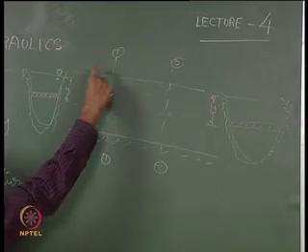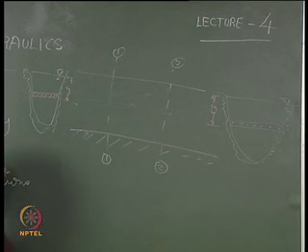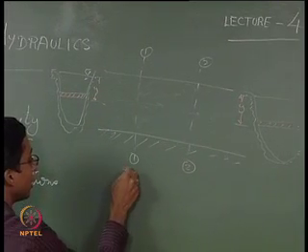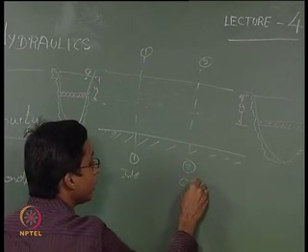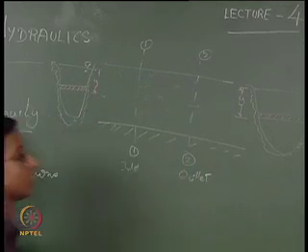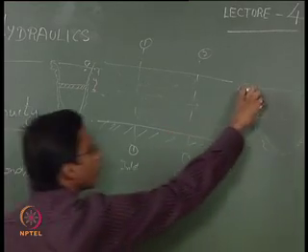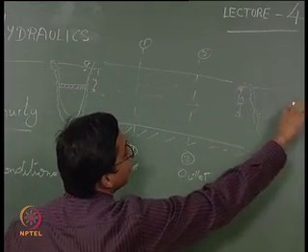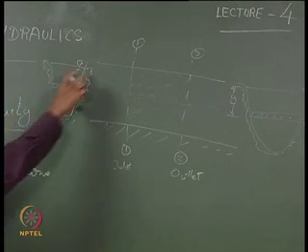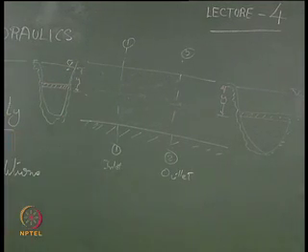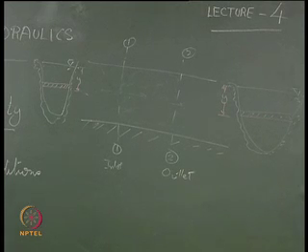This is y at the section 1 that you can define as inlet, and this section 2 you can define as outlet. So, this is the depth of flow at the concerned point at outlet, and here this is at inlet. Using this you can just integrate to find the entire area and the mass coming out.